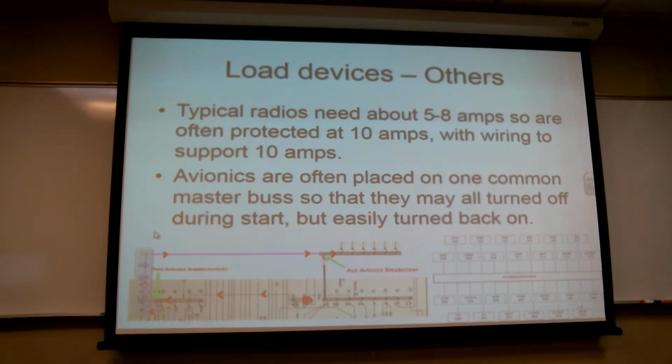On the other hand, all the avionics combined add up to 45 amps, and the starter puts out 400 amps. Now you've got an order of magnitude bigger, and when that thing shuts off, anything that's attached to it might absorb some of that kapoof, that magnetic field collapsing off of that 400 amps as it shuts down. So yeah, typically the off is worse than the on, but sure.